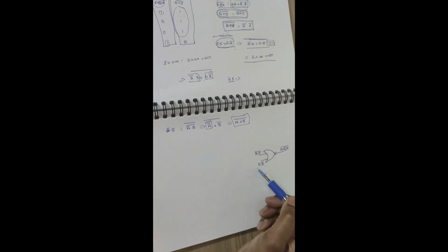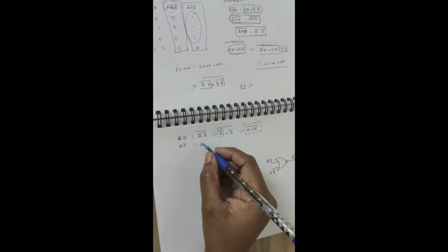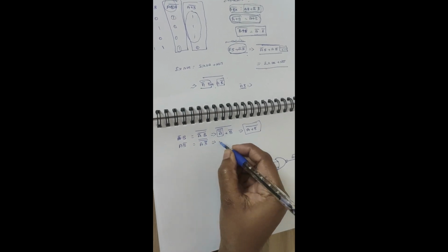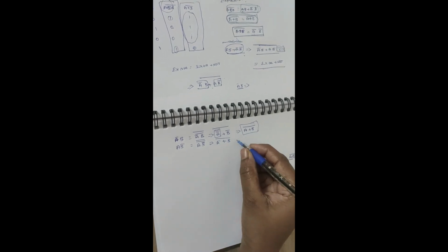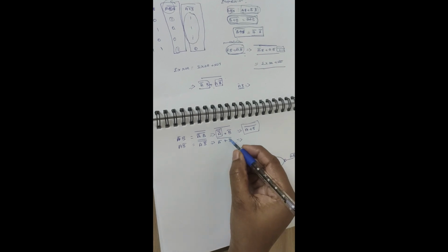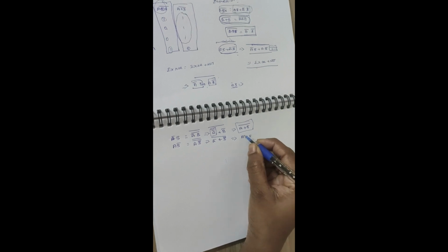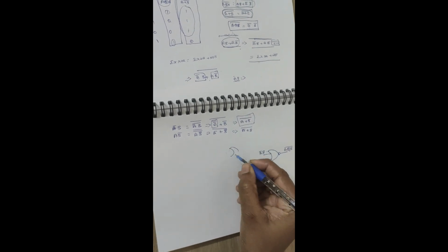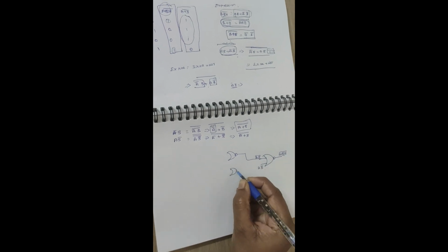Same as that, for AB bar we'll convert it into NOR format. With double inversion, converting this, it will be A bar plus B bar, the bar; B bar, the bar gives B only, so the double inversion. So A bar plus B, the whole bar. So we got the next level of that NOR gate. This NOR gate is giving to this one, and this is another NOR gate.